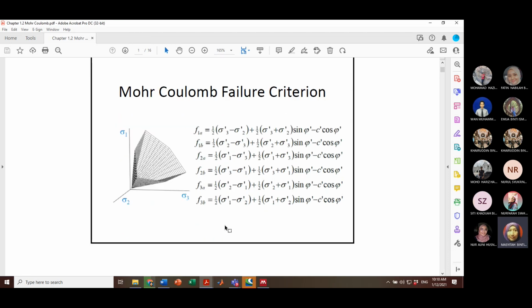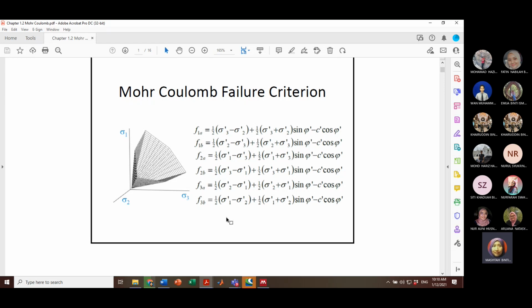MC, or Mohr-Coulomb failure criterion. It is a part of the stress path, and in this kind of yield criterion, you may see how the failure of the samples for these kinds of material behave. Either the samples behave linearly, or linear elastic, perfectly plastic, or you may see that it has strain hardening or strain softening, or the material behaves with linear or non-linear characterizations.